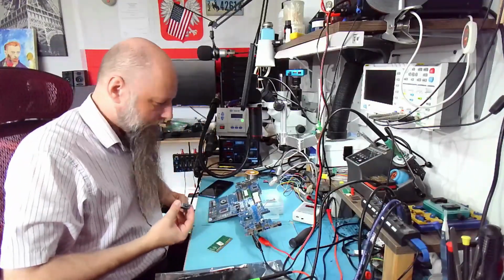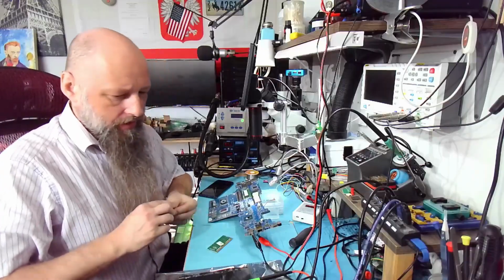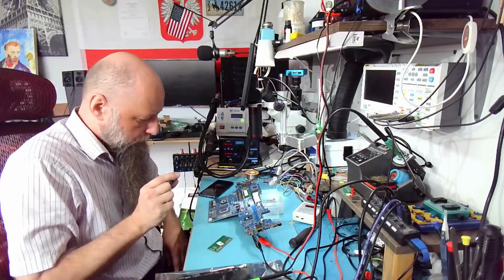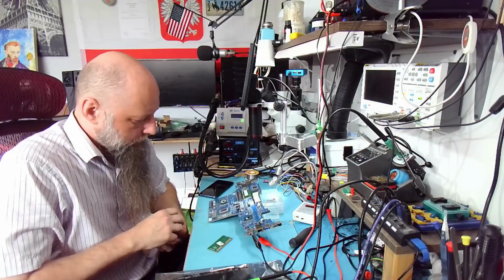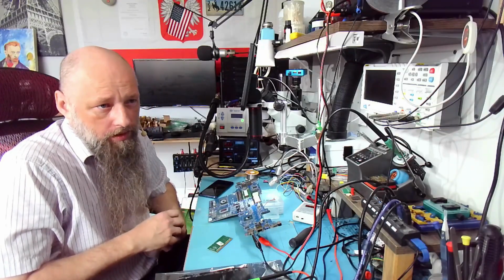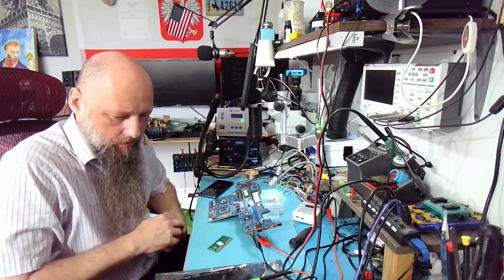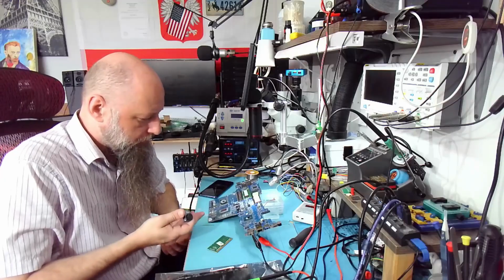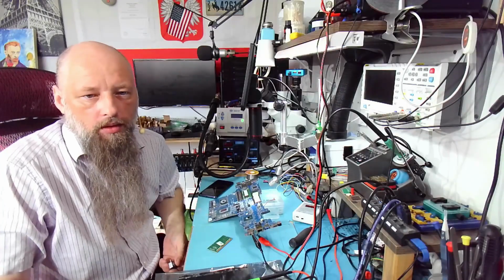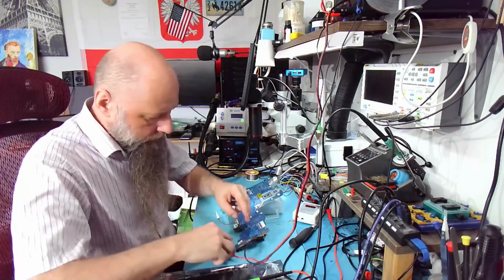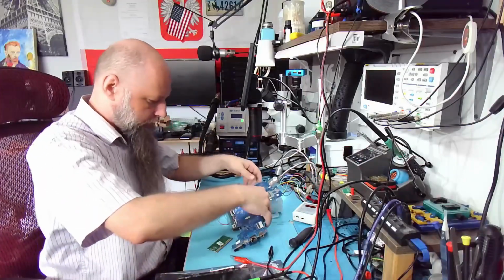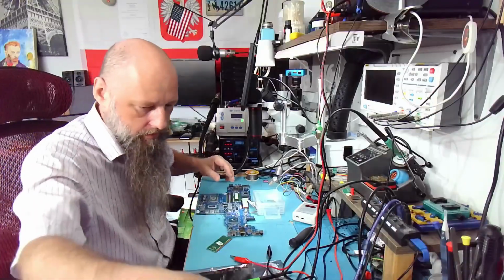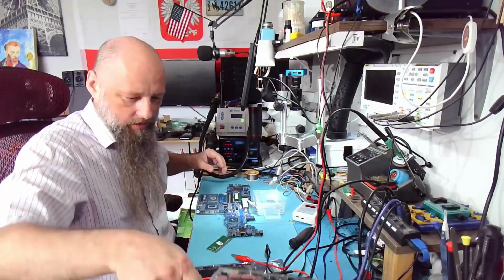Okay, that's enough. So here is what I see. If we push it all the way to roughly 3 watts, we see the core lighting up. So I'm not sure why my resistances seem the same on one and the other when I check on the caps. But when I check on these resistors, it's lower. Let's consult the schematic again. It's starting to look like it's the GPU that is fried. But if that be the case, let's do some more measurements to confirm.